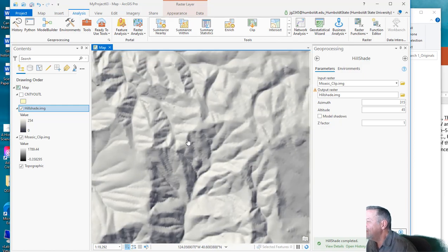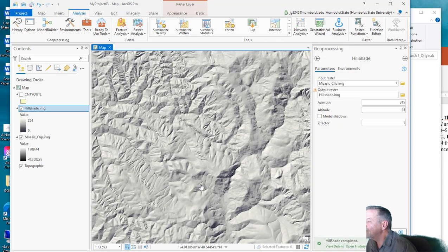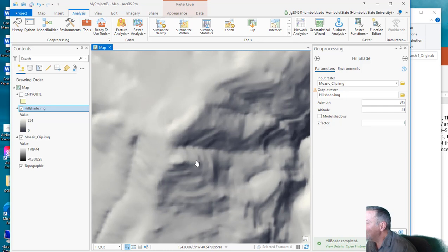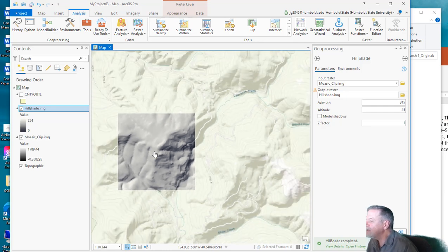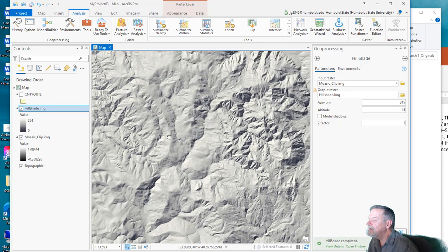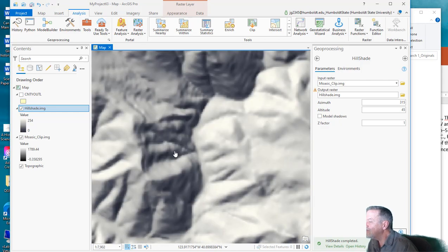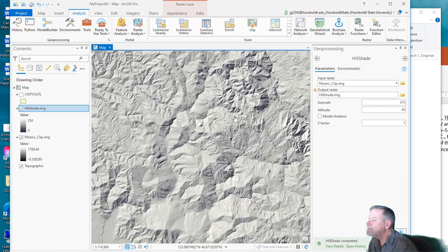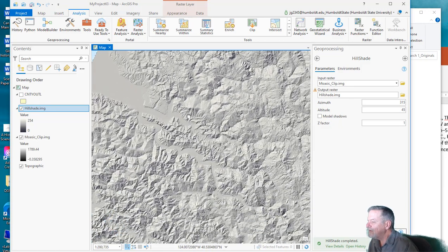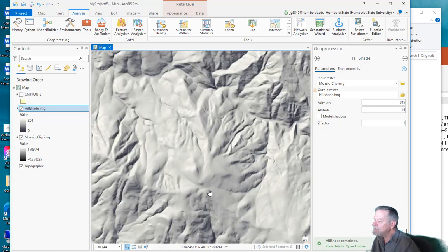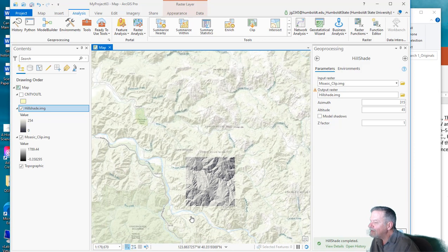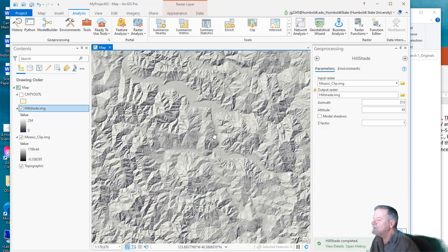And in fact, it's good to check as soon as you download the DEMs. These funky lines that we're seeing are actually artifacts in the DEMs. We're not sure why the 10-meter DEMs have them, but there they are. So we have to deal with them, but they're not too bad. And since they're not systematic, they don't tend to mess up things as much as if we did projection with like nearest neighbor. Okay, so I think we're in good shape.